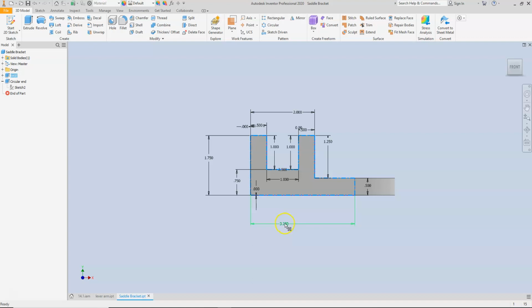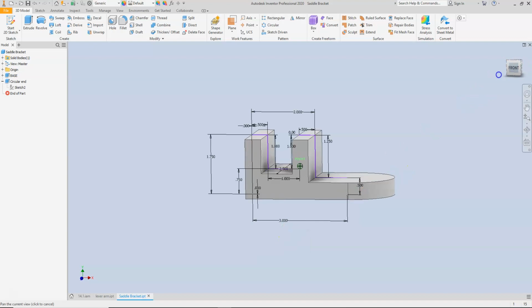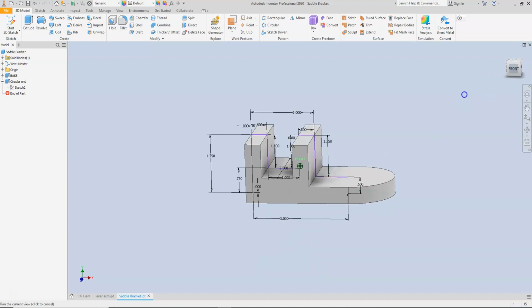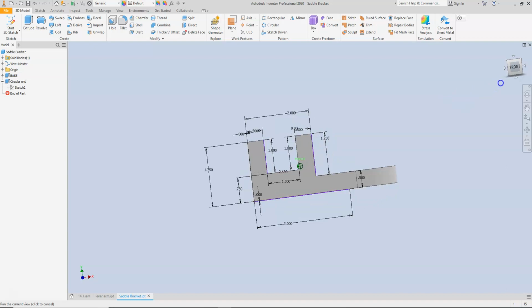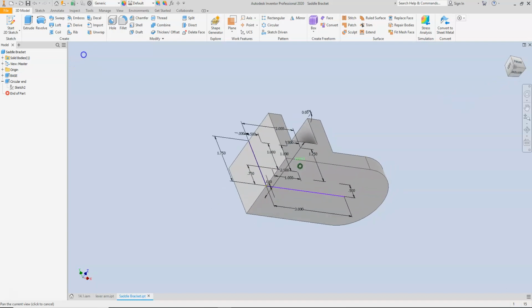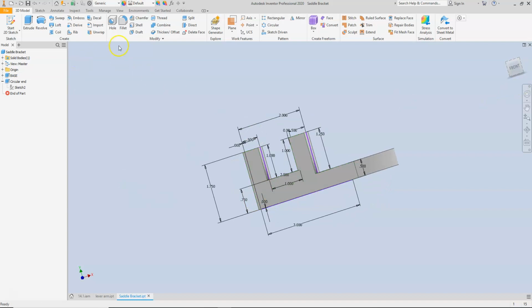finishing the sketch, simply click on the dimensions in this show dimensions, and you can change the dimension. Once you change the dimension, the part will not immediately update. So I changed the value, and the part will actually update after I make the change. I've got 3, and in order to get the physical part to update, go to your local update button up here at the top, and it's going to regenerate this part as per the changes in the dimensions.